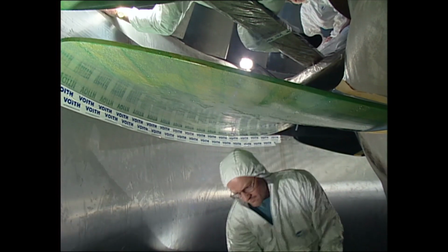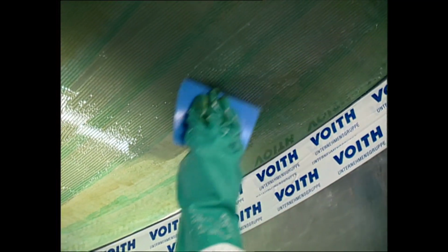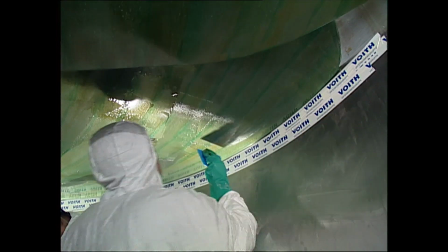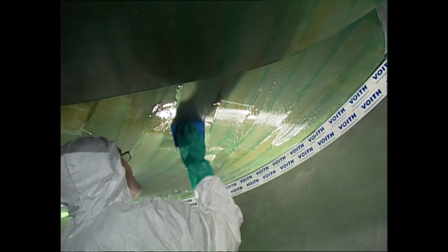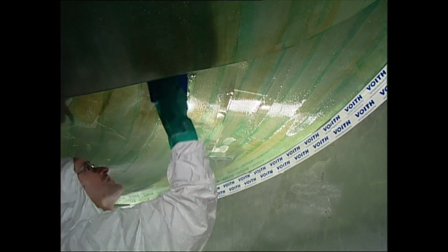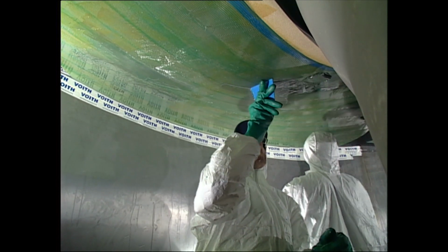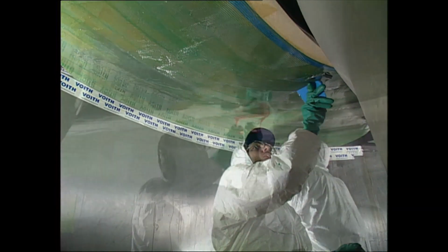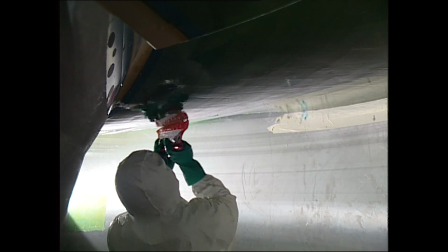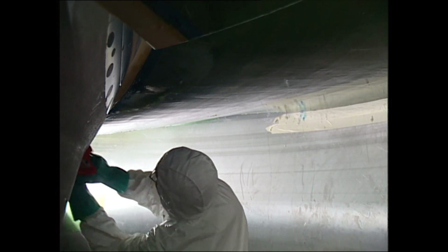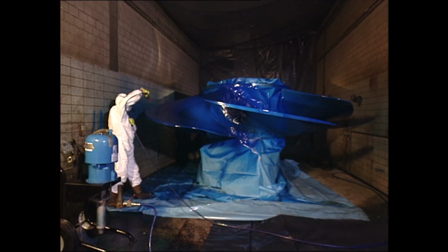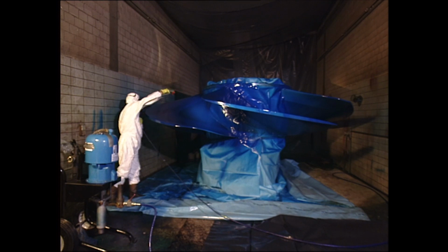The final protective layer is applied by troweling. This is done using a multi-layer technique in order to build up a coating layer of about 1.5 to 2 mm thickness. The final surface finish is achieved by using appropriate smoothing trowels. The application could also be realized by means of airless spraying.